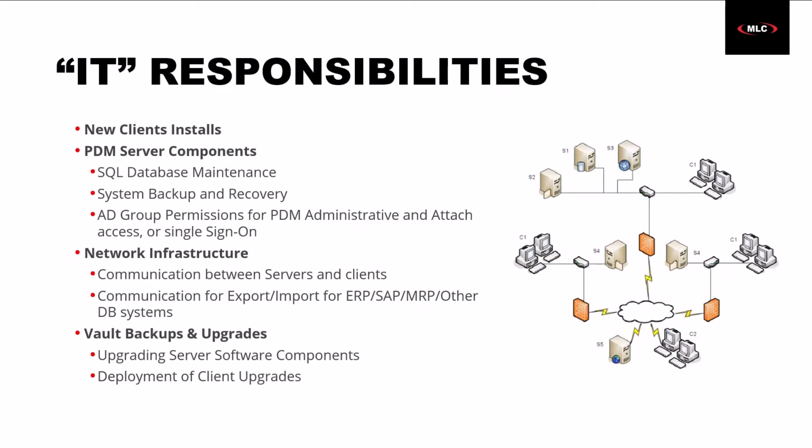When it comes to PDM Standard and Professional, there's a little more to manage on the IT side. For starters, PDM admins are tasked with installing software for anybody that uses PDM, and because this resides on a server, they also have to maintain that PDM server with items like SQL database maintenance, system backups, as well as overseeing the network infrastructure to ensure that client PCs remain connected to the server. For PDM Professional, admins might also be responsible for managing PDM logins through Active Directory, or managing how PDM communicates and integrates with other systems like ERP.